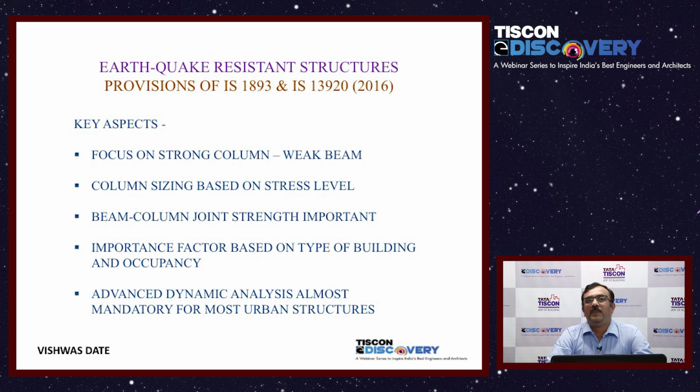Column sizing now is based on stress level. It is not purely based on loads. It is not purely based on P and M character. It is also being based on stress levels. Why? Because it has been found that columns which are slightly oversized perform better in ductility. We'll talk about ductility a bit later.